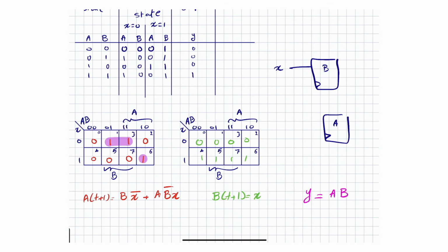How about the A? The A is a little bit more complicated. It'll take the value of B into an AND gate, not with an X in here. And then we're going to combine these with some sort of an OR, and the OR will get 3 signals, or actually 1 signal, but it's like 3 ANDs. So you get the value of A from here, and the value of B bar, which you can take from the Q bar, and then X. I'm just simplifying it by writing it this way.